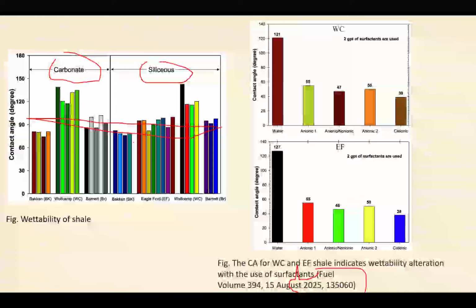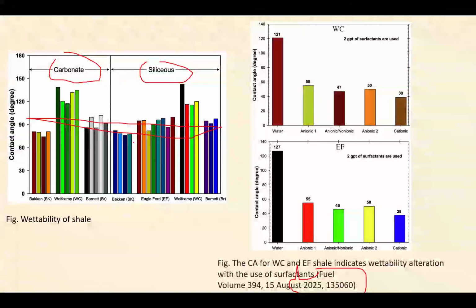Now, the selection of the surfactant is very important. For that you have to perform different studies so that they get attached to the rock surface and displace the oil from the rock surface, and accordingly that is measured by the change in contact angle.